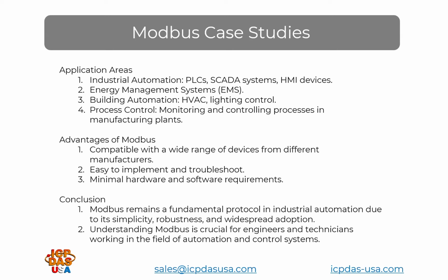Ideally, I like Modbus tables that start at 1 and just have sequential registers that make sense. And then usually configuration may be a different block, but those registers are less used. But the most common ones, ideally you want them to start at 1. If they start at some funky number, it may take some troubleshooting. Worst case scenario, just pull one register at a time.